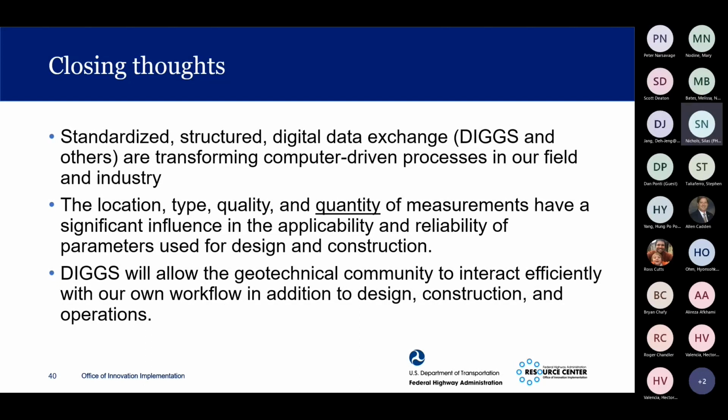It's that we don't do a very good job of understanding deterioration of assets, right? The reason why transportation asset management works is because you're looking at deterioration over time as part of your strategy of managing the asset. We look at things as pass/fail, right? Because it's impossible to look at a slope and determine that it is somewhere along a path to failure. It's either stable or it's unstable. And so data management as a construct would ultimately be a central piece of geotechnical asset management, or the geotechnical aspects of transportation asset management, but we aren't there yet.